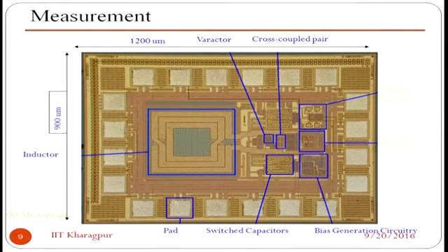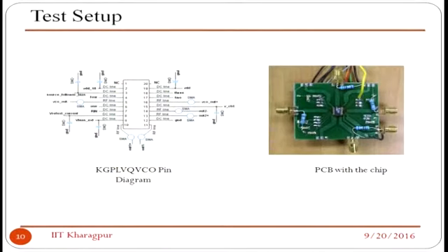This is a 180 nanometer National Semiconductor process, 1 volt. Mind it, the challenge of the design is that this is a 1.8 volt supply, but we are designing it for 1 volt only, so we restricted our voltage scale to 1 volt. So after the design, then you have the pins.